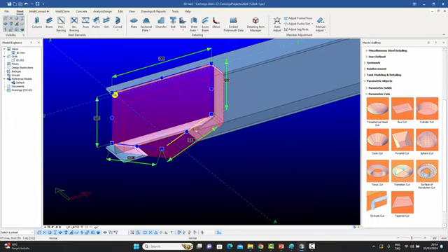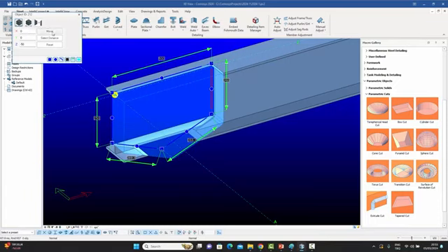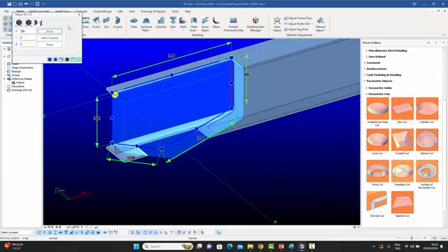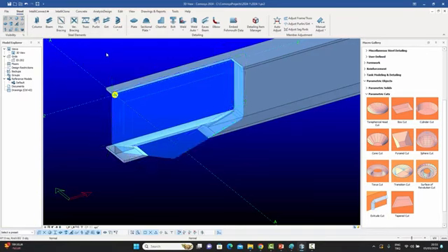the definition points on the screen, and you have the handles on the screen. You can give chamfers to the corners. You can insert new points in the cut. You can move entire lines. So this line, for example, if you wanted to move it to the right, all you needed to do was, for example, reset this and say move it 100 in the X direction, and it will go 100 in the X direction. So this is very useful. And the availability of on-screen editing for cuts as well will really make the job of the detailer a lot easier, we believe.